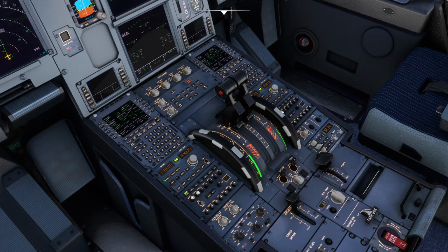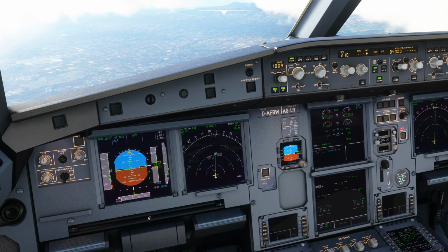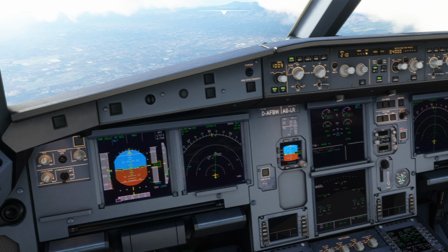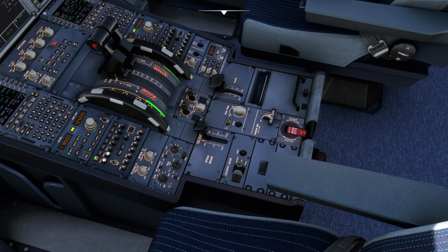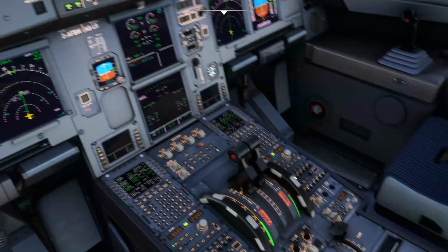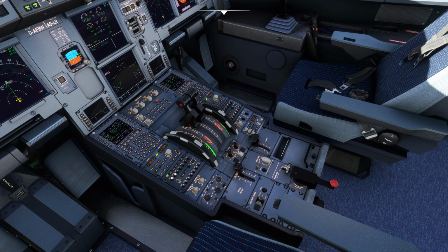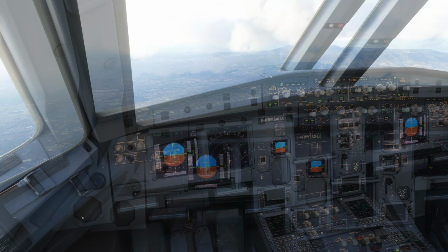Let's move on to what that handle actually does. What we're going to do with the handle is raise it up. When the time comes, you raise it up. You wouldn't do this in advance. And then you're going to turn it 3 times clockwise. And that is basically it. It's incredibly ingenious. Most commercial aircraft have gravity gear extensions that are not as well designed as this. This is a fantastic system. It's very easy to use, very simple, and very robust.